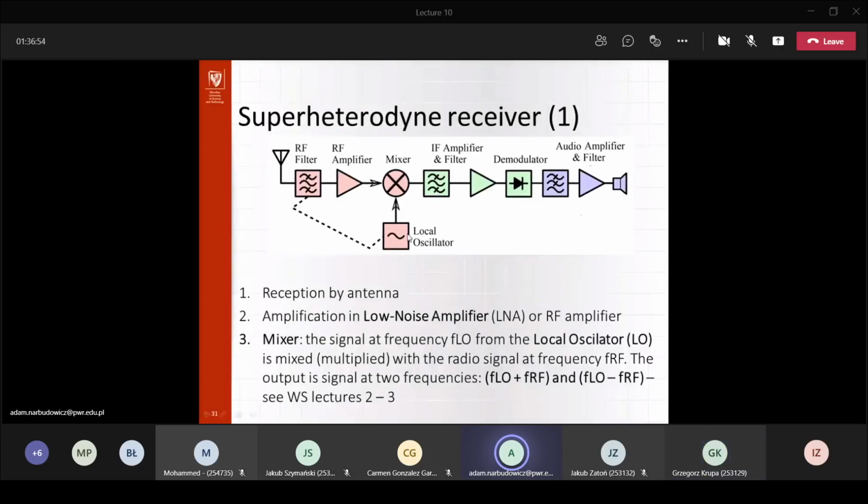With the mixer, you have to be careful, because you actually need those nonlinearities to generate your signal. But then you should design your filters carefully, to pass to the next stage only what's useful and needed, and filter out all the intermodulations, which in the case of third-order intermodulation might be challenging and might sometimes require a narrow pass filter.